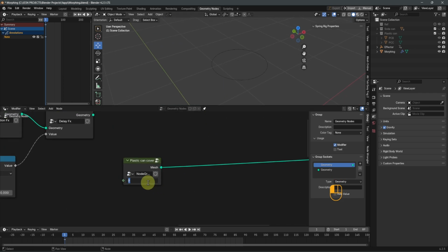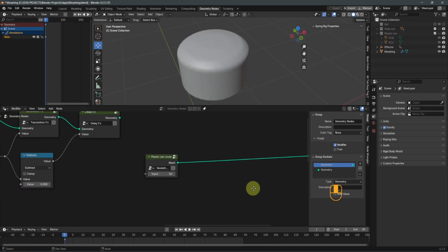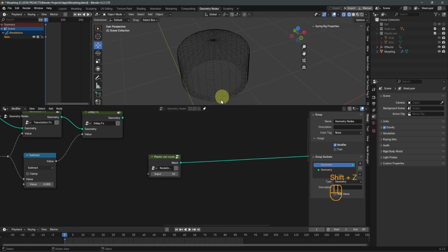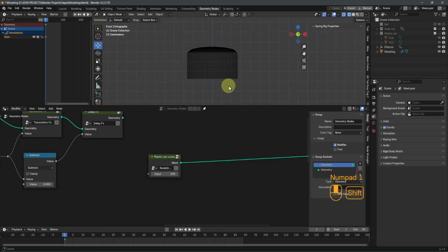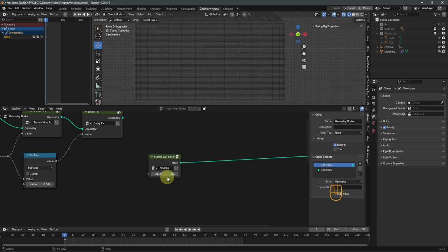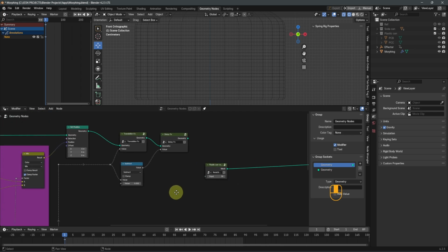But now if you put in a value here, let's use 50 for example. I think this is better. While I use 50 is because if I use 200, you see the mesh is dense. I don't like this much dense mesh, so that's why I'll use 50 for now. If I have a problem with the transition effect, or as the case may be, then I can easily just make it 200 with the others.